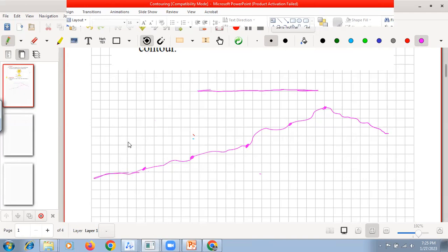For example, we set our equipment, that is auto level, at this particular point. After leveling and all the setting of this equipment, this level is perfectly horizontal. We see from this end, and as this is perfectly leveled, whatever you see will be in one horizontal plane, and we use the staff over here, and we measure this reading.